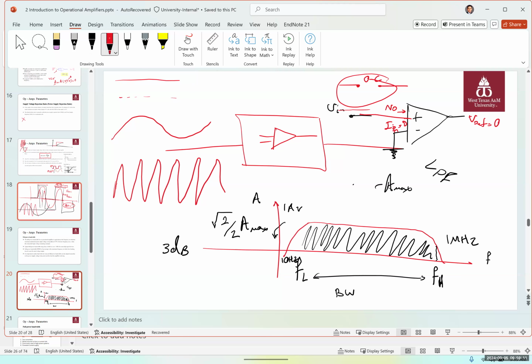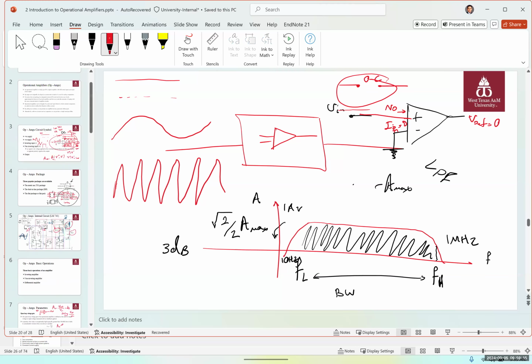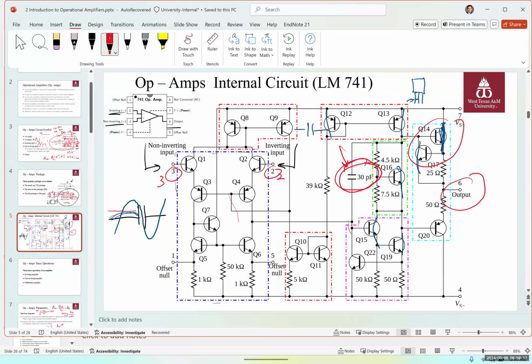And the high pass filter and the higher cutoff frequency is determined by the inner capacitors, like these small capacitors that exist between the pins of a transistor. As I mentioned before, in very high frequencies, the terminals of these capacitors, because they are metal, create a capacitance.